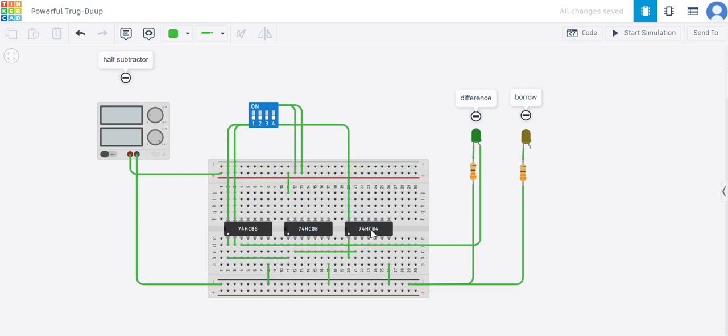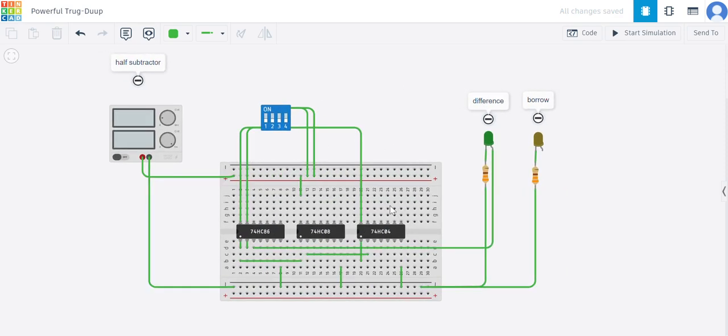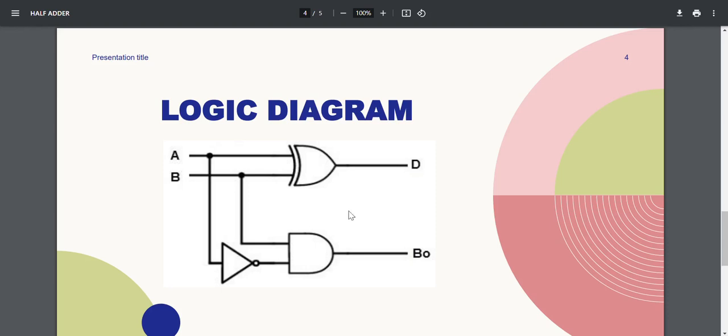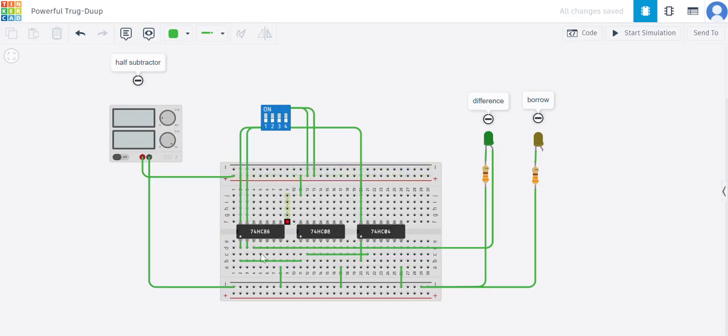of the other input. So here we made one mistake, and I did it purposely because we have taken NOT of the second input, and here we need to take NOT of the first input. So it was a mistake done purposely, so we can change it. Now the input 1A comes from the second input, and the input 1B must be NOT of our input 1.